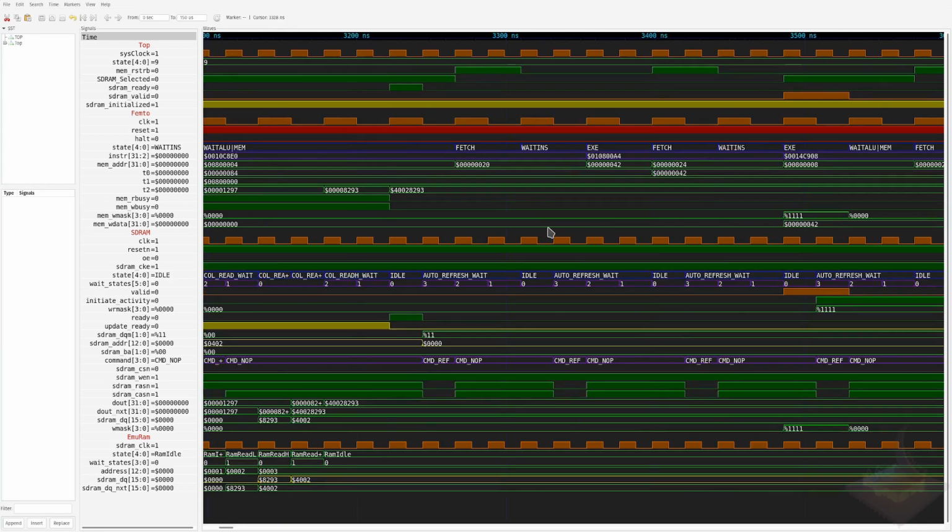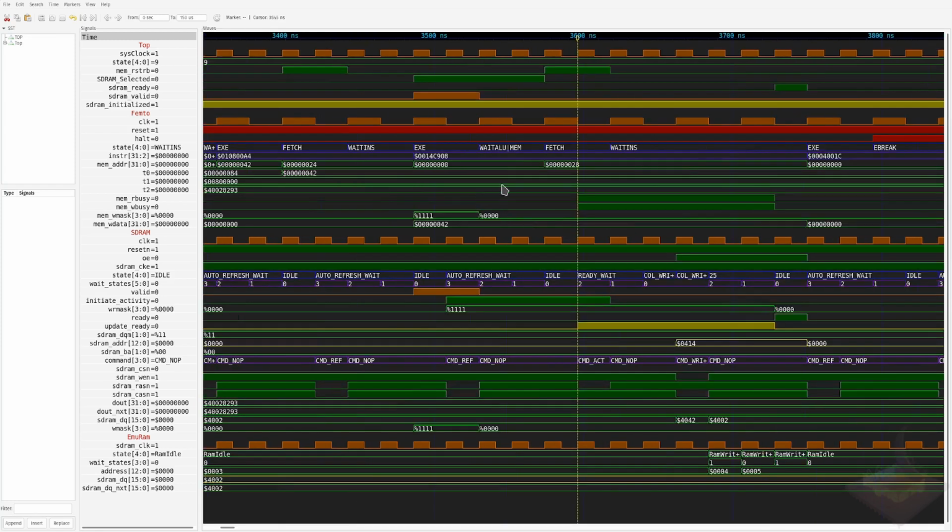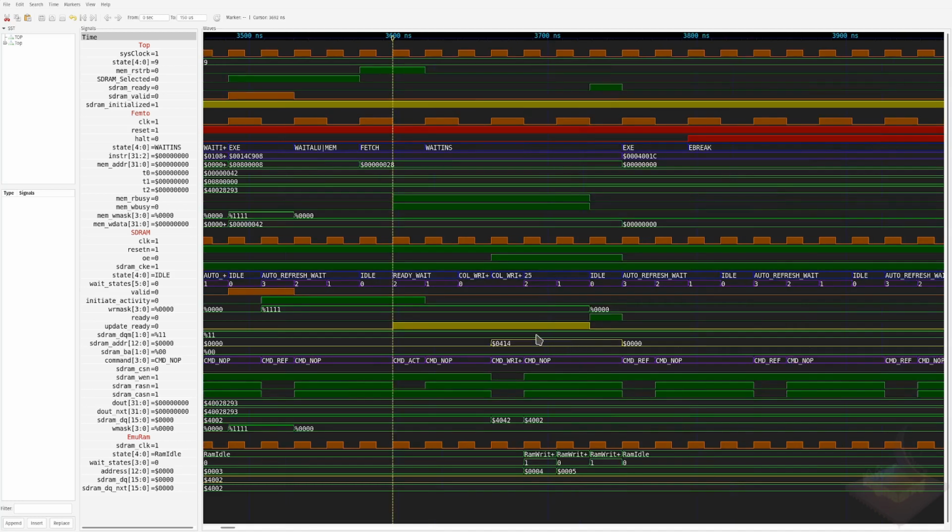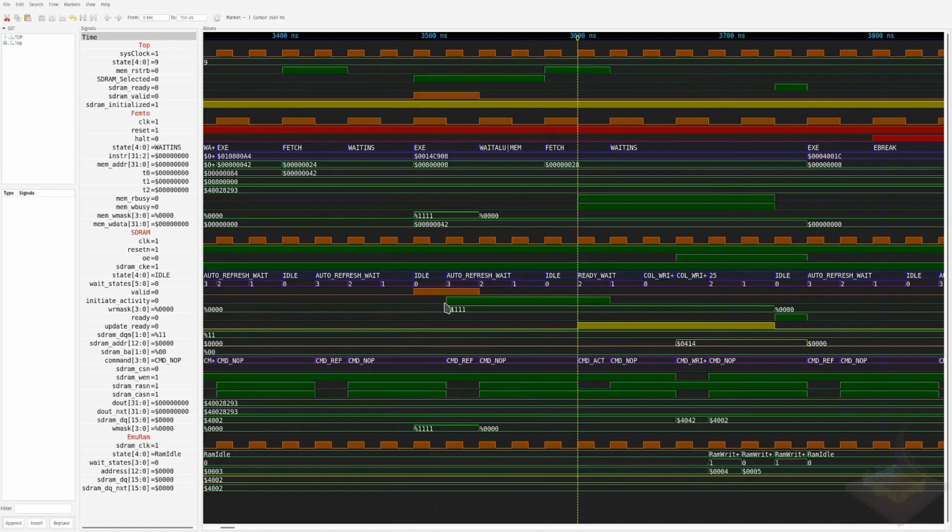This is the typical sequence, and we also know that the code had a write sequence in here, and that's where it's doing it. You'll notice the write sequence is shorter in duration, because the SDRAM chip has internal buffers that grab the 2 bytes and then go on its merry way. And of course, you won't be able to do anything while it's writing. If you try to quickly turn around and read from it, you would find that the SDRAM is busy, our signal would be high.